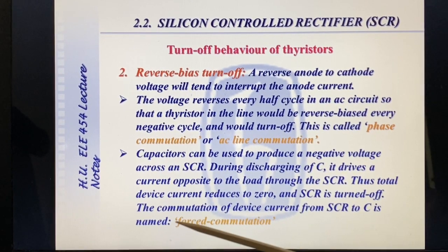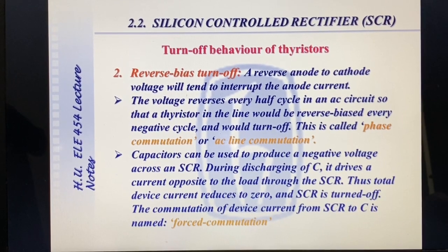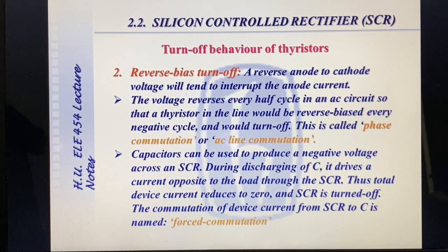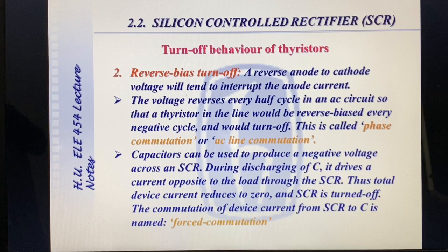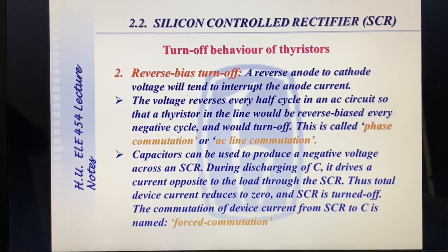There is also a forced commutation principle where negatively charged capacitors are switched across the thyristor, but this requires complex circuitry and therefore is not very much preferred nowadays.